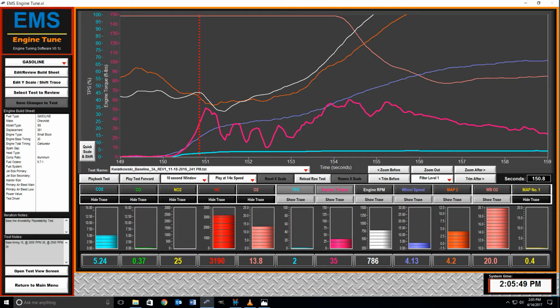For the condition that we call porpoising, we're going to take a look at our test graph from the 150 to the 154 seconds. What we will do is look at the torque, the engine RPM, manifold vacuum, and wideband. We will finish up by looking at what the gas analyzer tells us, to give you a better indication of the secrets of the gas analyzer and its ability to help you resolve the problem.